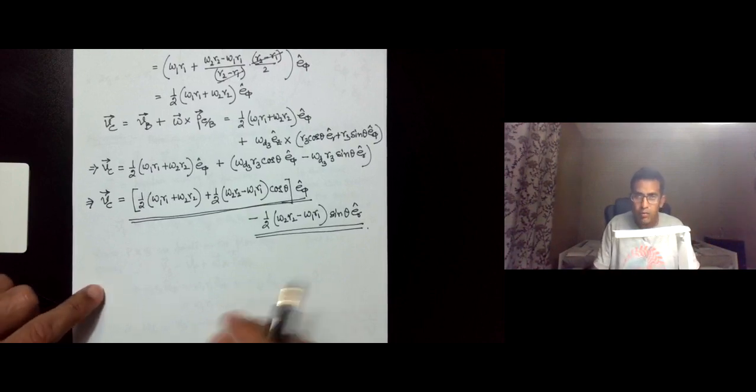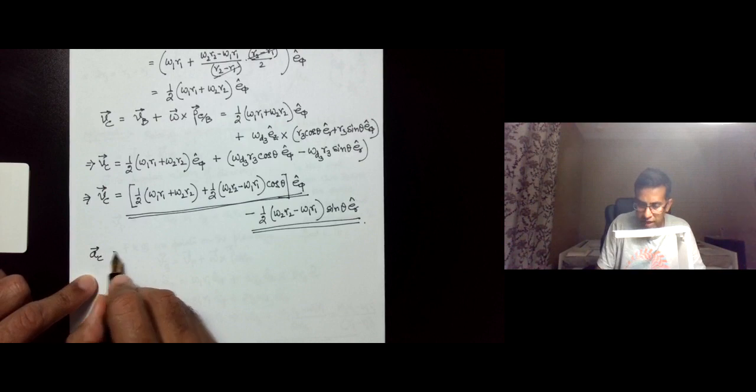Now in the second part we want to determine the acceleration of the point C, and we are going to proceed with the same rotating reference frame, but now we are going to move on to the acceleration equation. So we are going to again express AC relative to AB. So AC is equal to AB plus, let's write the full 5-term expression, and then we will remove the terms that are not relevant. Omega dot cross rho C with respect to B